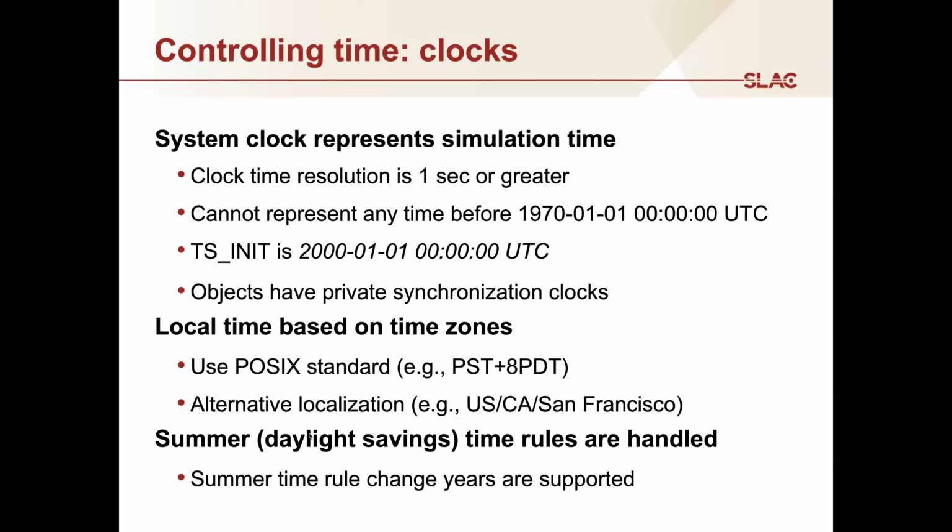One very important thing to understand is the way daylight savings time rules are implemented. Unlike tools like Excel, in fact, most tools on systems, the daylight savings time rules change from year to year. So if you run a simulation, for example, before 2006, you will see the daylight savings time rules that were in effect at the time.